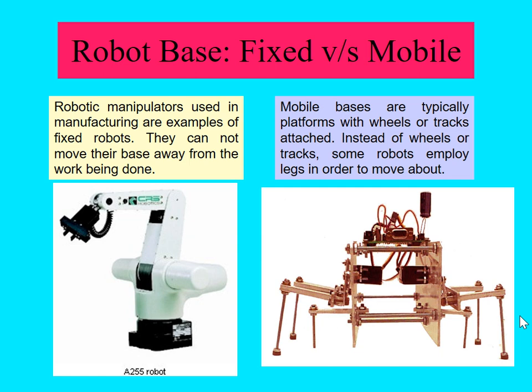We see 1 degree of freedom where the white meets the black, and again I can't draw because we're on a projector here, but where the white meets the black, that rotates a number of degrees. I am guessing it's probably 270 degrees, not a full 360. Anytime you start rotating 360 degrees, then you run into the problems of cables twisting. So most robots only rotate 270 degrees or even 300 degrees.